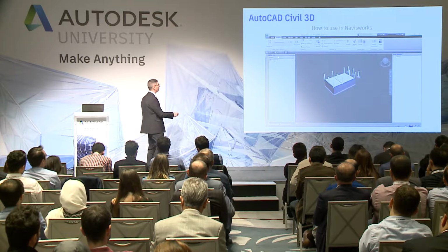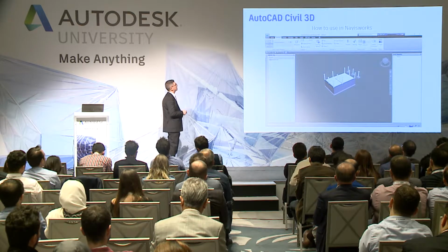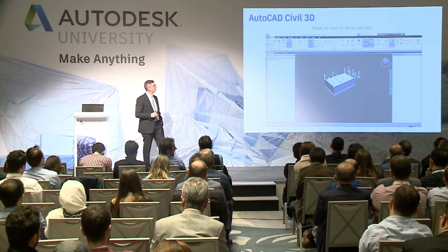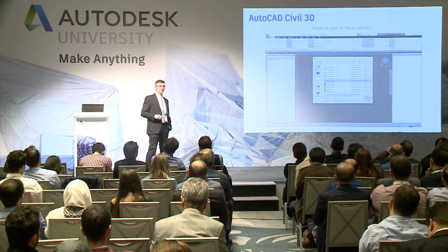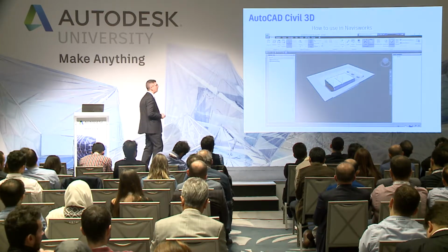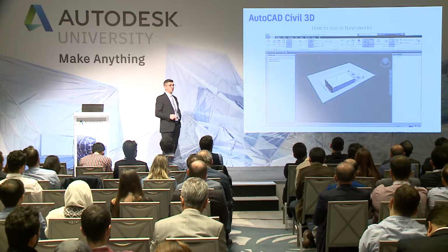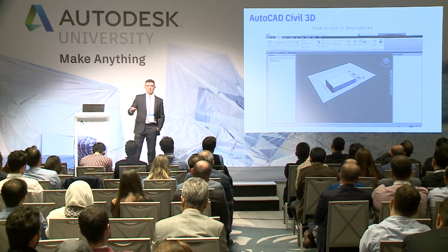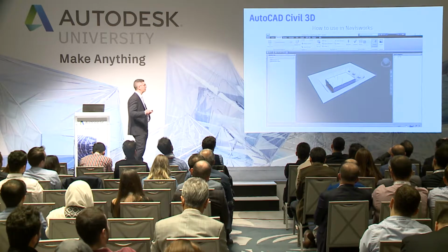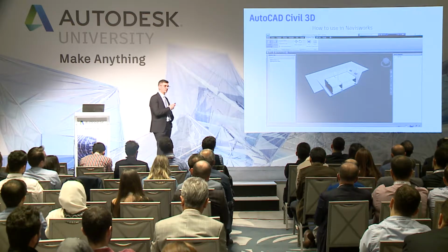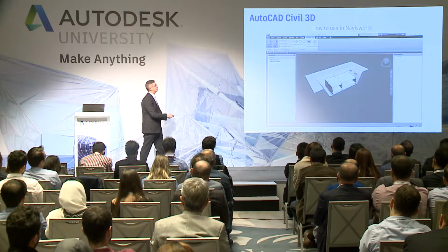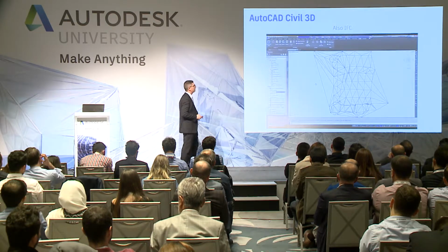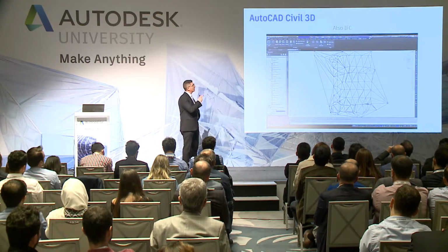This is a Revit model, OK? And I can go on the Home tab, Append, and then I take my excavation to understand what happened, maybe for safety, like this one, OK? And then I can manage it and start here, I don't know, creating 4D or 5D, or creating a timeliner inside my model. Like this, it's a shape and a section.